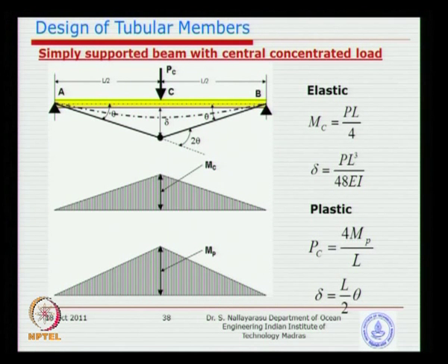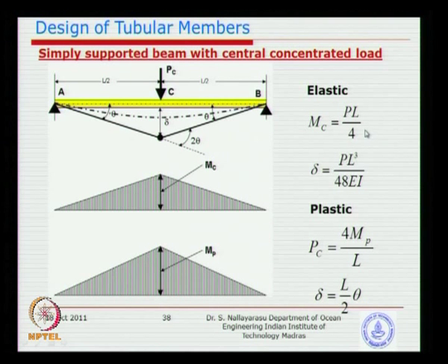Now, this is the state that we are interested in when a structure is designed, for the many methods which we have to discuss today. Particularly, we are looking at the state of stress at the working load versus the state of stress when the structure is collapsing. The larger that margin is, the better, so that we have extra margin to satisfy. So, this particular concept of a simple bending moment diagram, all of you might have studied in applied mechanics.